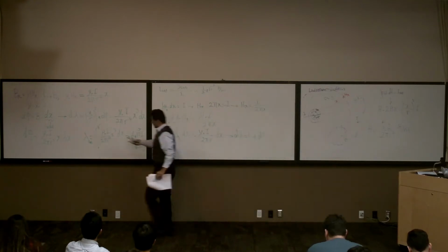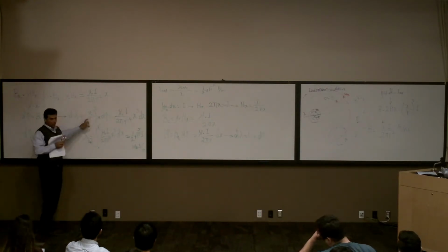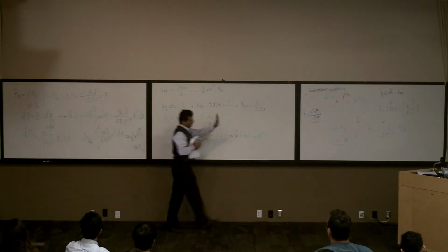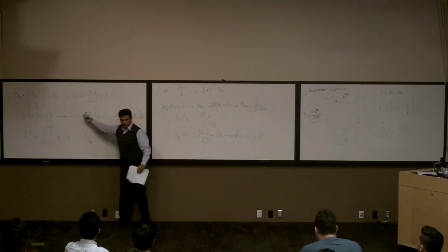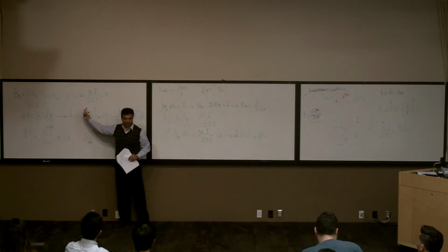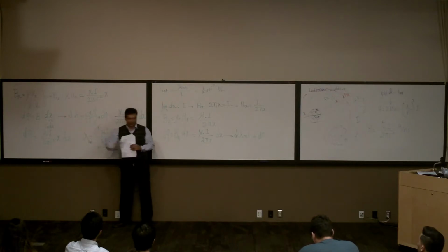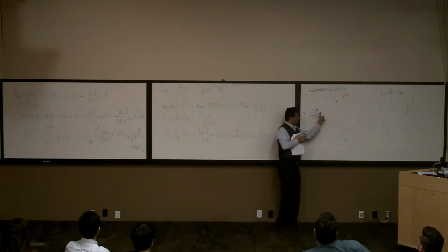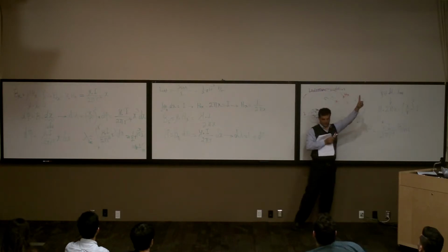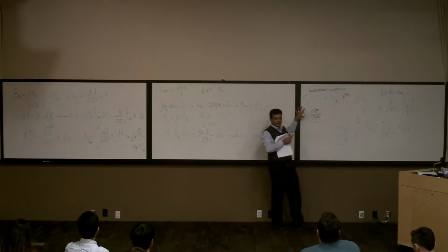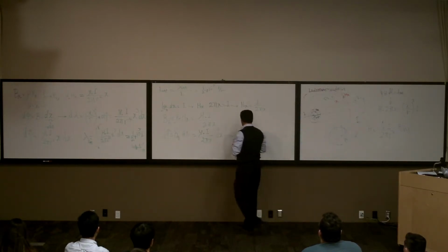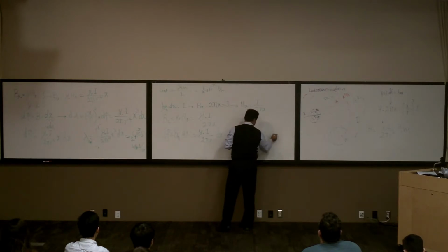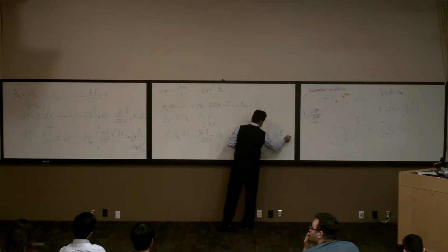Basically, if you look at it here, it says x over r. As soon as you go outside of the conductor, how much is this x over r? As soon as you are outside the conductor, it is 1, right? Because you are either just here or here or here, there is no difference, right? For all of them, the current inside the loop is going to be I, right? So d lambda is going to be equal to mu0 I over 2 pi x dx.